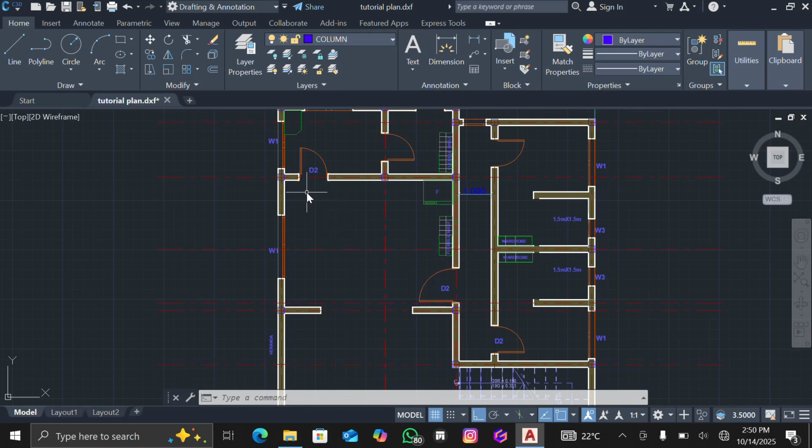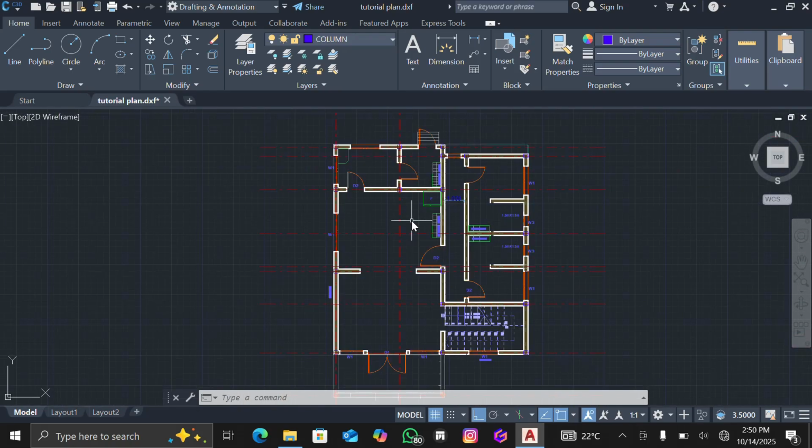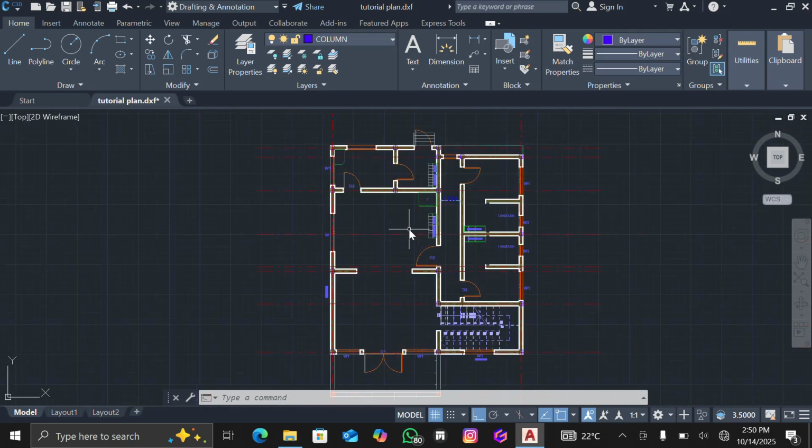Also, during the implementation of the work, take an example. You specified a certain spacing between one reinforcement and the next in your slab, and then the people who are executing the work maybe decide to increase it. Maybe they were told it should be 150 or 200 millimeter, then they use something like 300. That can also lead to the effect of vibrations. You understand? So basically that is it.